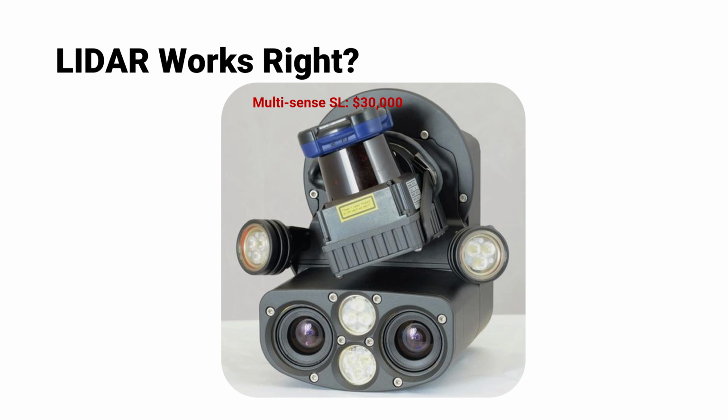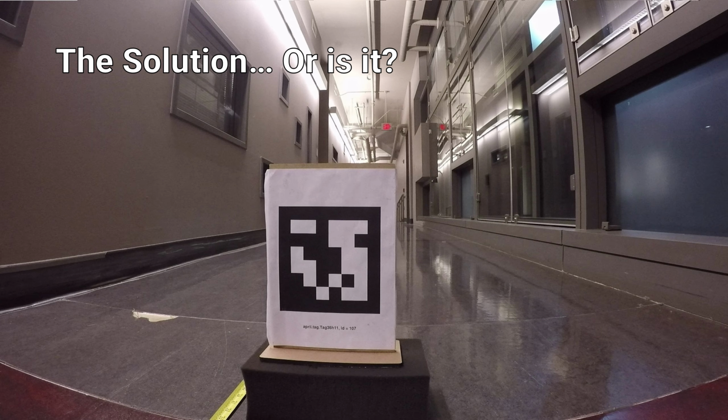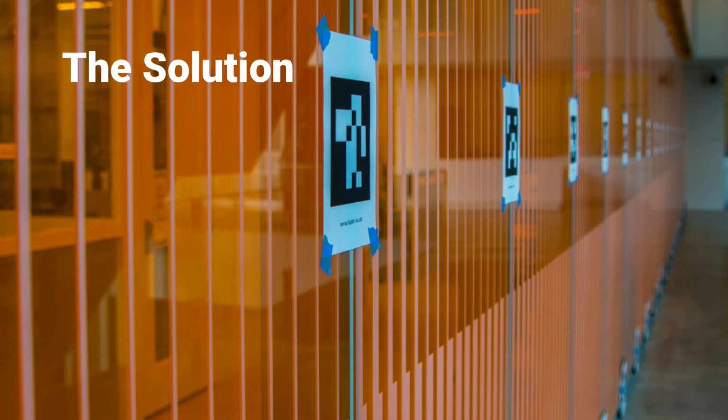So we were like, okay, can we do something better? Can we go back to basics and look at visual fiducial markers like the AprilTag? And we thought, hey, can we just use one simple AprilTag to do this? As we found out, the accuracy was not that great. So instead, the solution we resorted to was basically to have a row of AprilTags. We did not want to cover the entire scene with AprilTags because that's doctoring the entire scene. So we laid them out in a way that we could strategically place them with minimal coverage, but just enough for our solution to work.